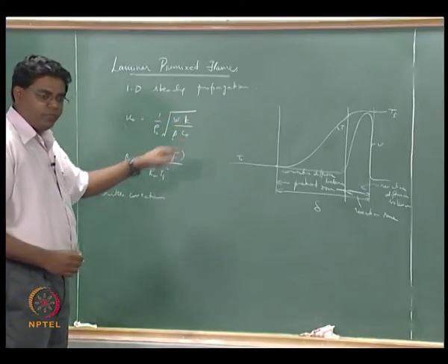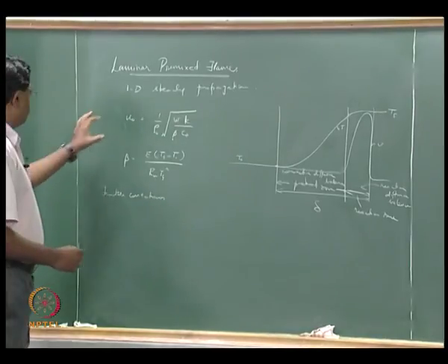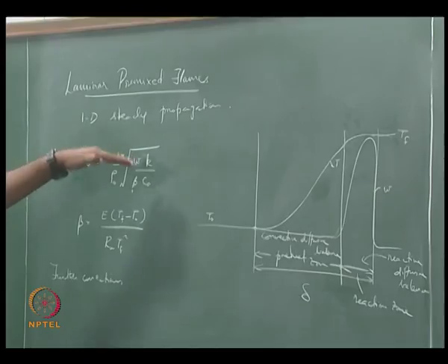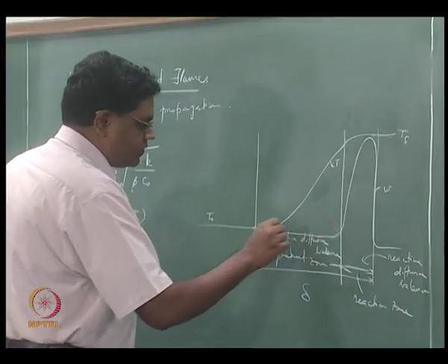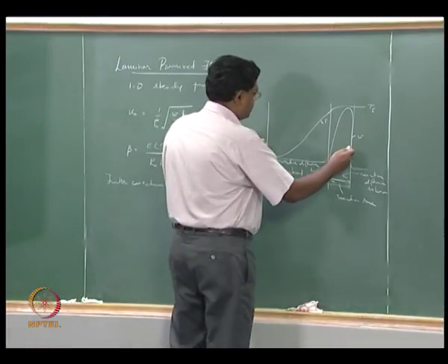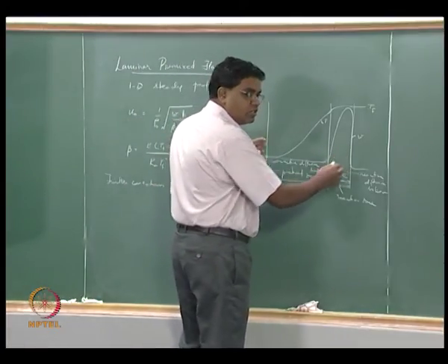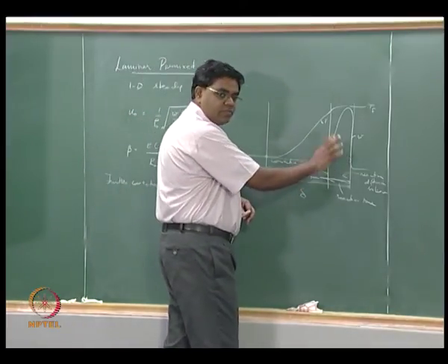And so we now notice that the flame speed is about that much smaller, right, because we are now factoring in that reactions are happening in only part of the flame and not in the entire flame. We could now do further corrections by noting some more things. First of all, what we had done was to assume that W is a constant across this region, and now what we have said is W is actually a constant across this region approximately.